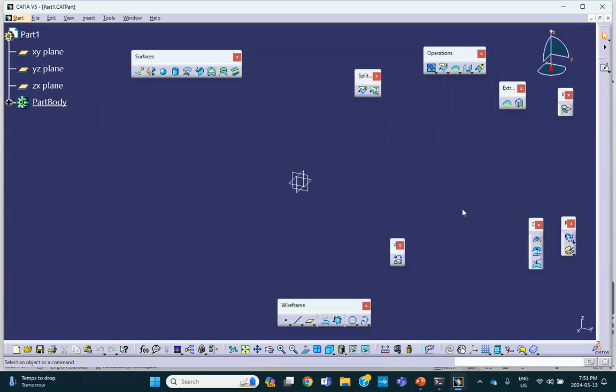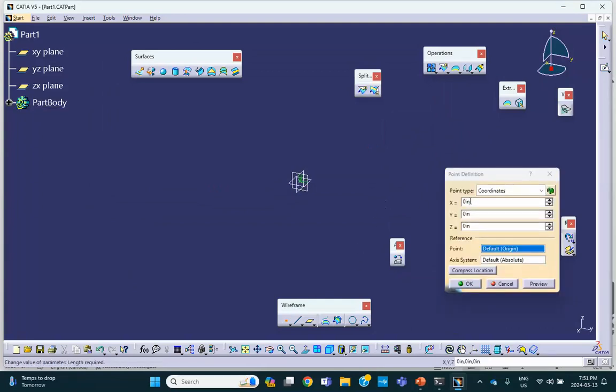All right, let's create the points. So where's the icon for points? Right here. Double click on it. Let's do point A, and I'm going to type in the coordinates because I already gave you. Point A has coordinates 0, -10, and 0. So this is -10. Point B has coordinates 0, -5, 0.